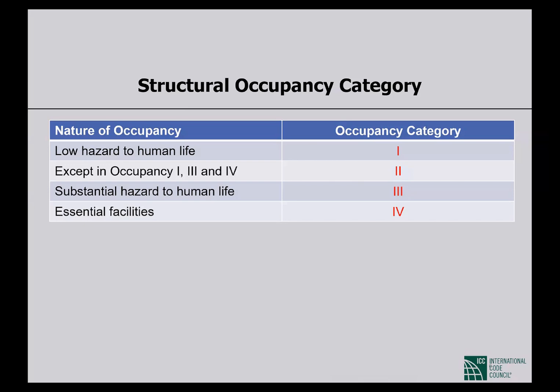For structural design purpose, the most important categorization is this, although the name is very similar to the architectural categories. That is also called building categories on the basis of occupancy. And in structural design also, we call it occupancy category. Basically, this is risk category. If a building collapses, what might be the risk? What would be the consequence of the collapse? It is related to this structural occupancy category.